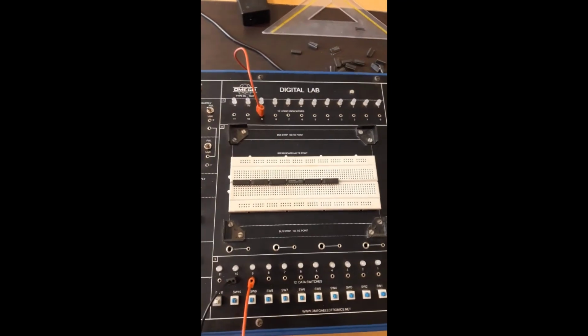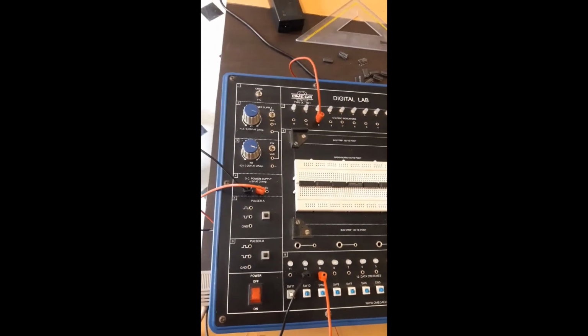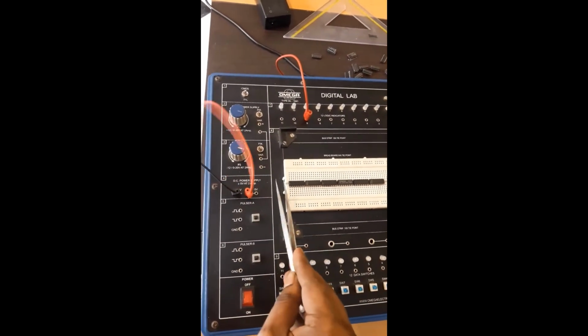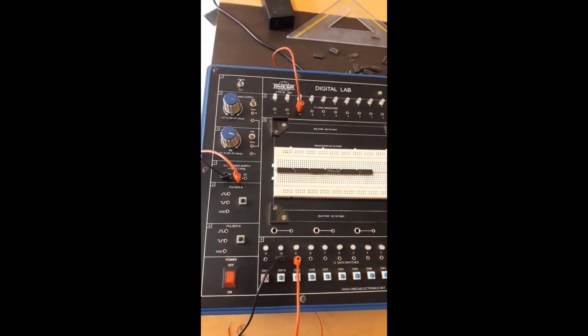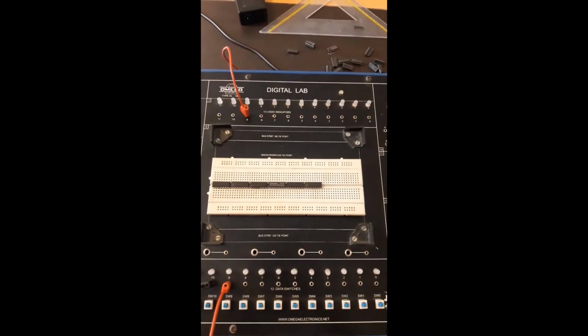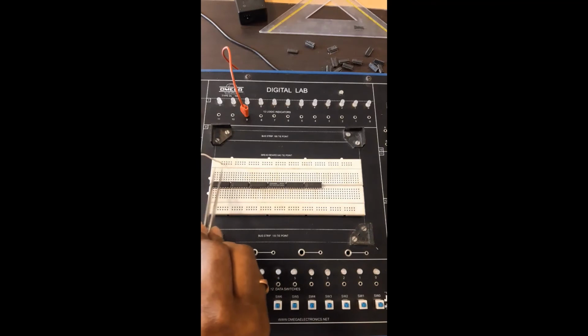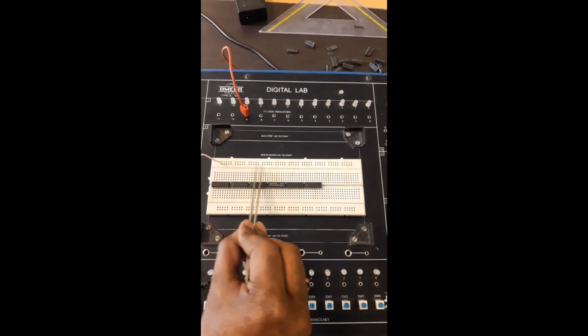And on this side, from here we will give the VCC and power supply. We need to give the plus VCC to pin number 14. So let's quickly give that. This is plus 5 volt and we will connect it with pin number 14. Let's make this line VCC. I have connected this point, that means this line became VCC.